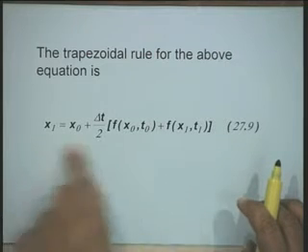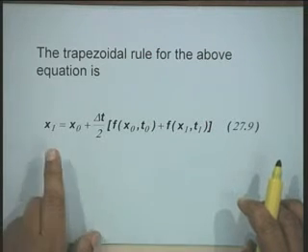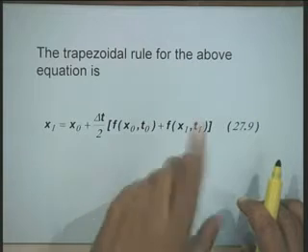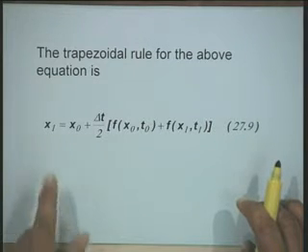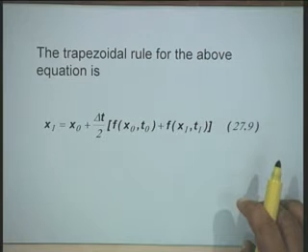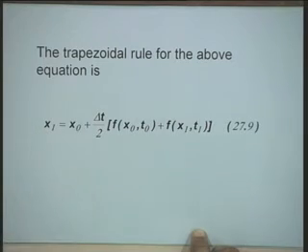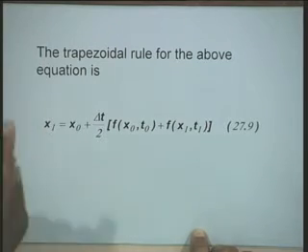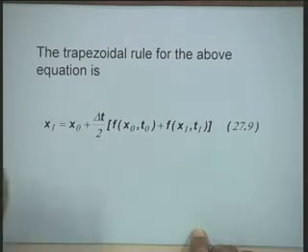In this step, x1 has been expressed in terms of x1 itself, but this equation is now an algebraic equation. This is a non-linear algebraic equation, and therefore it can be solved to obtain the value of x1 using standard techniques like Gauss-Seidel and Newton-Raphson, which are used for solving non-linear algebraic equations.